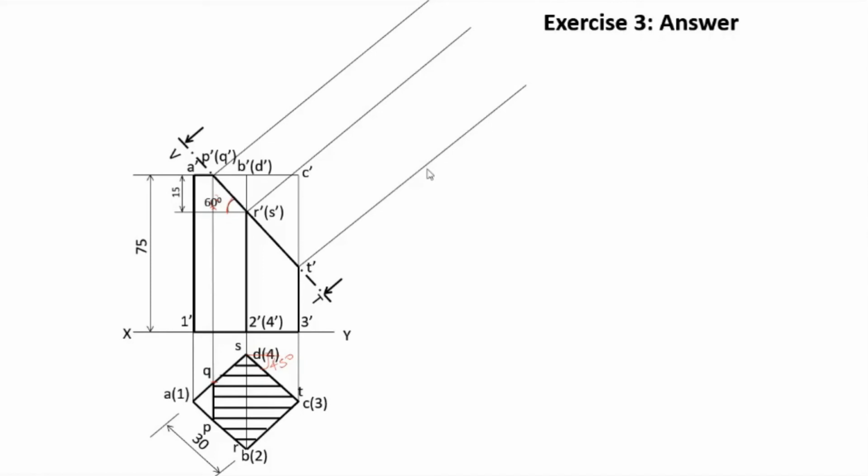Then from the newly generated points in the front view, draw perpendicular lines to the section plane, and a line which is parallel to the section plane, at a sufficiently large distance. It should not be too close nor too far away. It is better to keep it close to the front view, but it should not be too far from the front view.